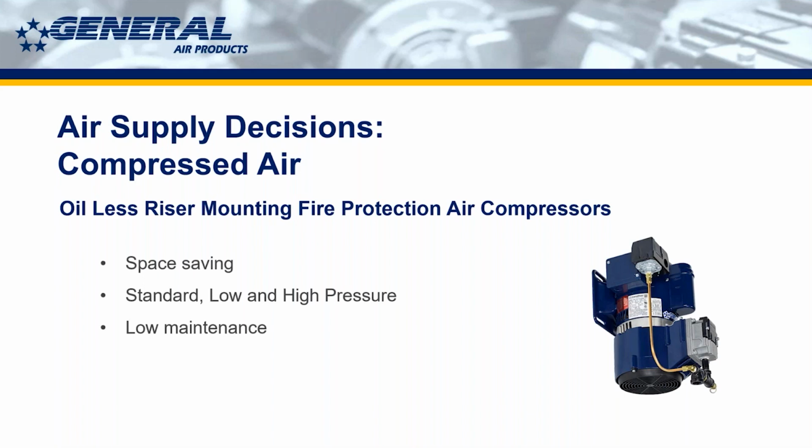So for all you designers out there, if you're laying something out, say with one of the Revit families, and you're dropping in a low pressure valve, make sure you're using a low pressure compressor with it, not just a standard pressure compressor. Ultimately, they're the same unit except for the pressure switch, so the size and everything will be the same.